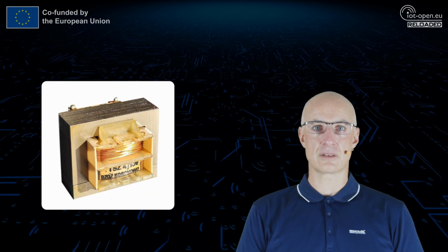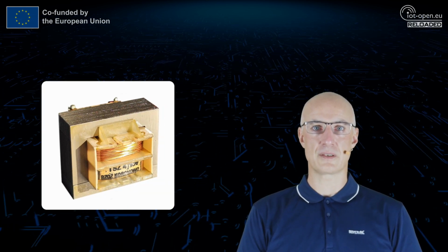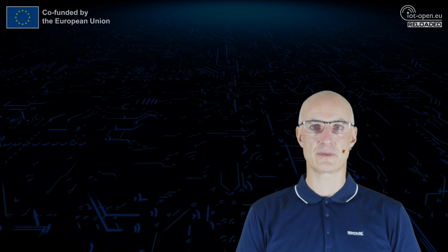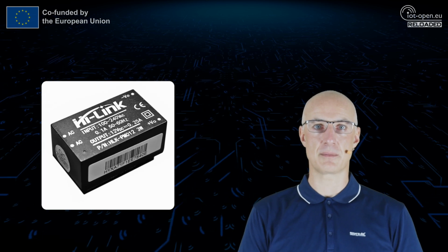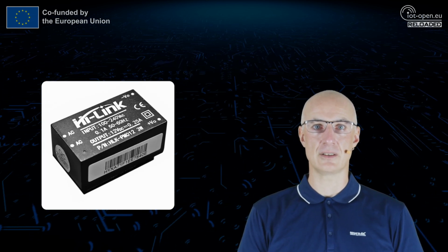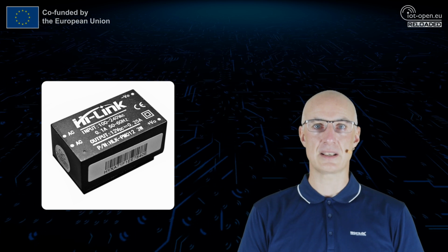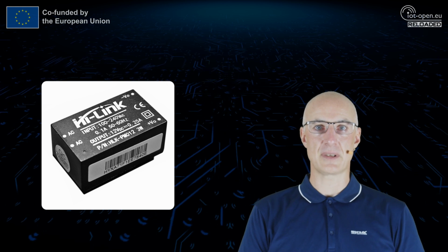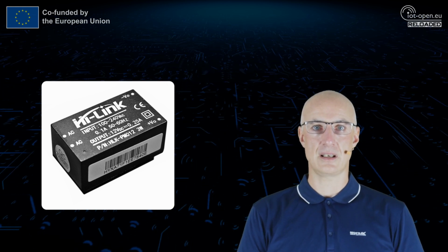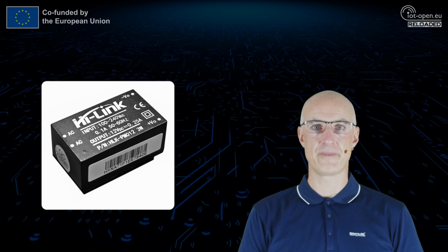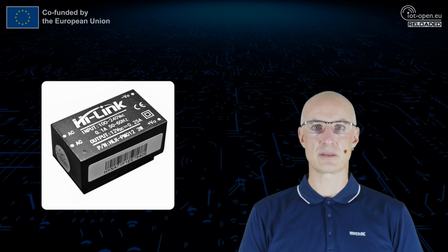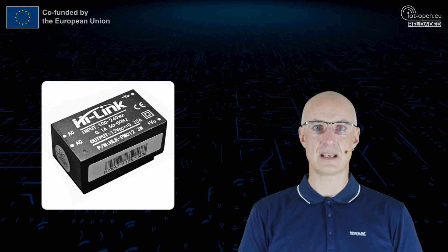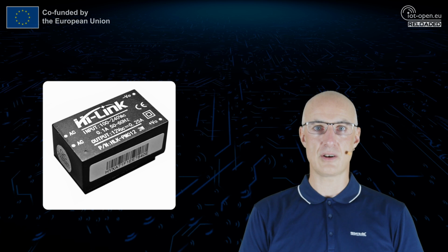AC to AC conversion historically used heavy transformers with fixed conversion rates and usually a steel core. Modern converters use a switching mode power supply that contains only a tiny coil. These converters are technically much more advanced, but they are also lightweight, accept a wide range of input AC voltages, and are cheaper. Nowadays, a switching mode power supply contains all components in a single enclosure, providing a stabilized voltage at its output.